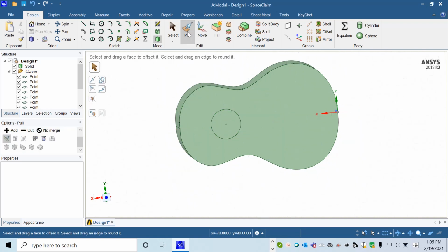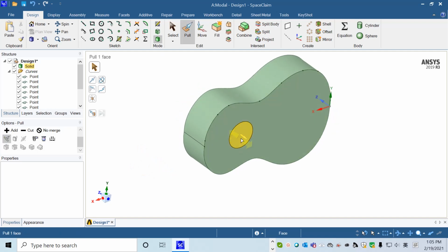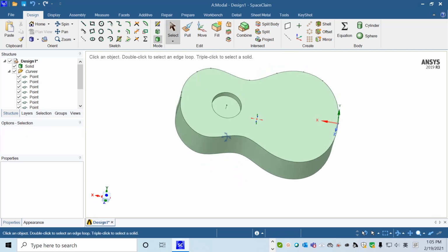and then click Pull, where we'll use this to cut into the solid. So where we can put a number, let's use 10. This geometry doesn't matter because eventually we will create a shell. So the inside of the solid should be hollow, but the thickness of the shell will be 3 millimeters. So any number larger than 3 millimeters will be good. Right? Now we have this structure.